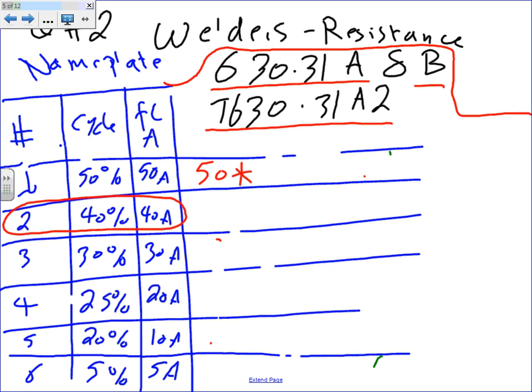We said for the first one, if it's a group installation, you allow it at 100%. Just the first one. So you multiply by 1. Then, based on the cycle of 50, what would the multiplier be? Anybody can tell me? 0.71. Thank you. Done. So that's based on the cycle. It's going to be 0.71, and that will give me 36 amps. Any questions, guys, about where the 1 came from? This one came because for the first, fattest, fluffiest, largest welder, you use a 1.